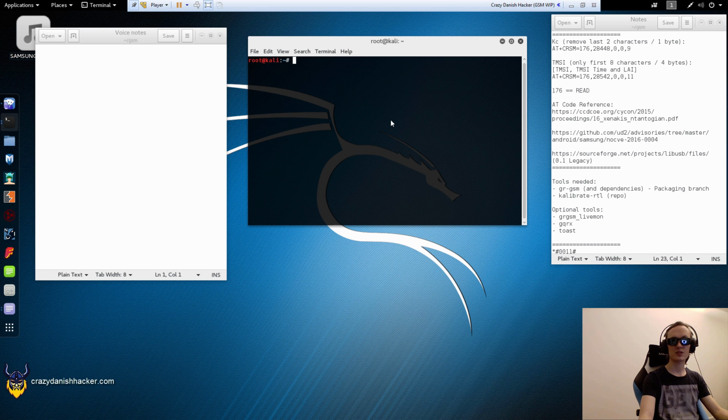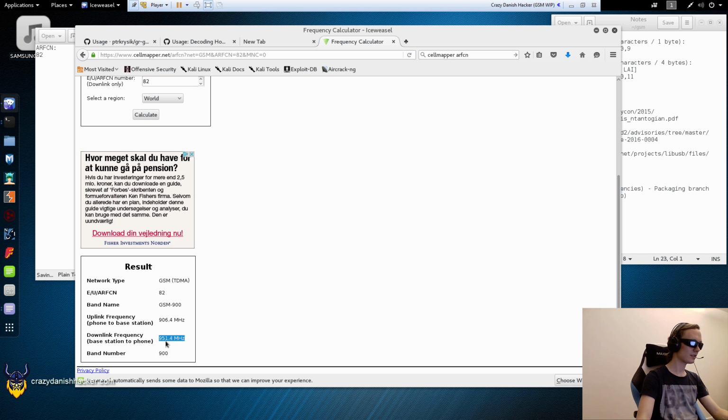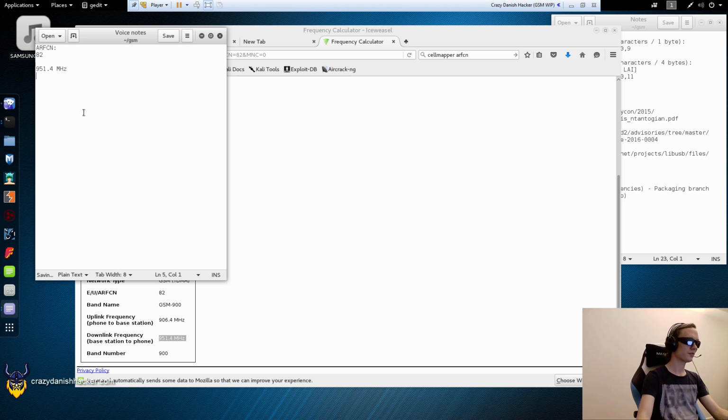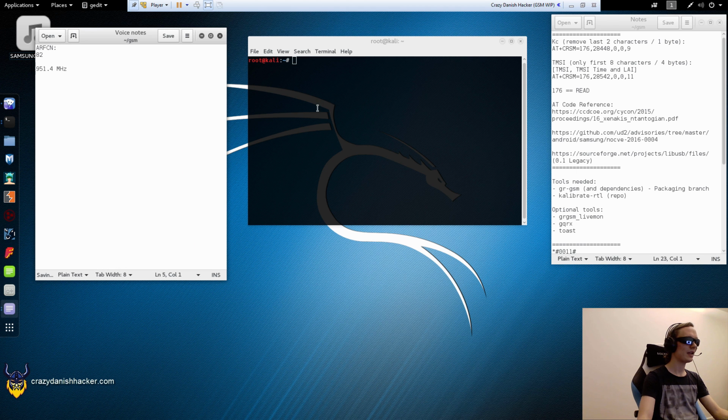Today we're going to look at sniffing a voice call and frequency hopping. First up, we are going to look at the channel in service mode, and that is 82. That's ARFCN 82, and the frequency for that is 951.4 megahertz. So here it is, and now we will just convert that to hertz. That's very simple. There we go.